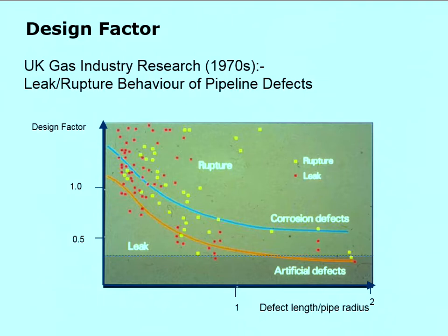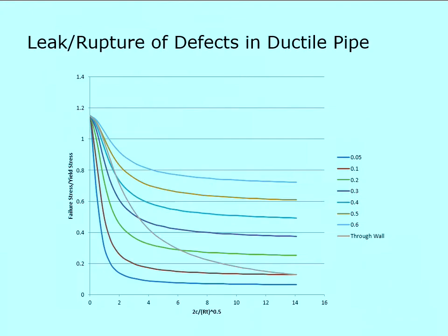Right, these, again, are old diagrams which were used to demonstrate this concept to the committee that was responsible for developing the code. So what we're looking at here is design factor plotted along the x-axis against relative rupture frequency on the y-axis. And you can see after a design factor of 0.3, the relative rupture frequency is very low. So that justifies that. In terms of wall thickness, we've got wall thickness plotted along the x-axis and the same relative rupture frequency plotted on the y-axis.